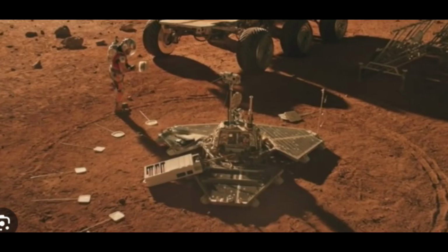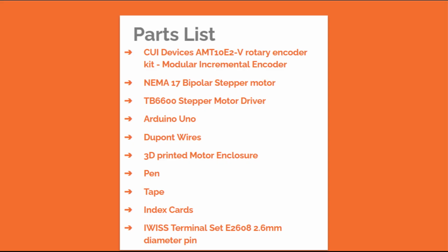In this project, we used a rotary encoder to track where in the circle of letters the motor-controlled rover camera would be pointing. We used an incremental rotary encoder which can transmit a motor shaft's rotational speed, position, or direction into counts per revolution. It has capacitive sensing technology, so the encoder uses the change in its capacitance value to measure displacement. Additionally, an incremental encoder allows for precise control over the motor.